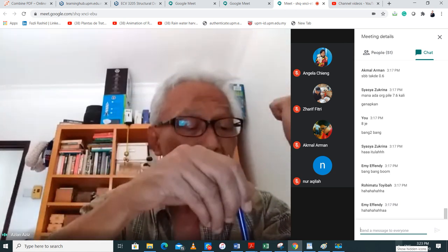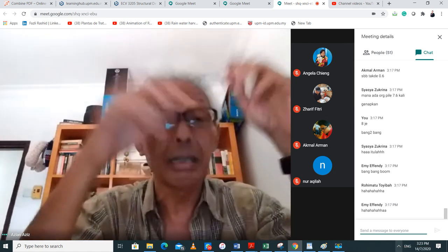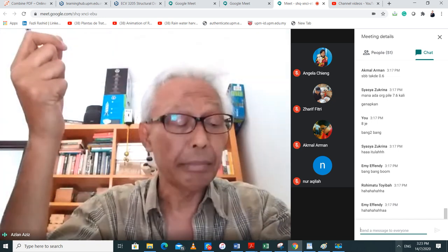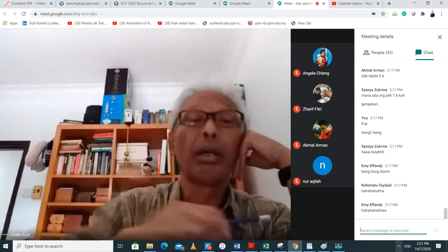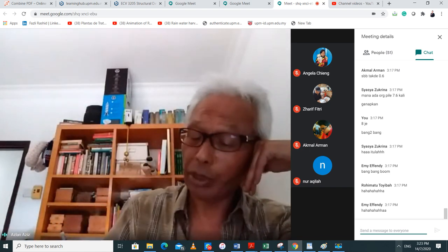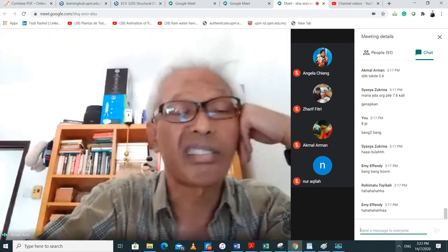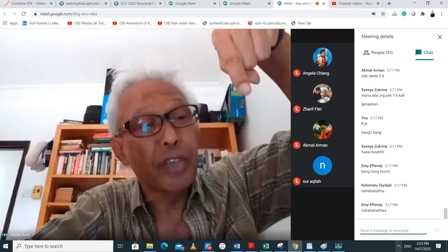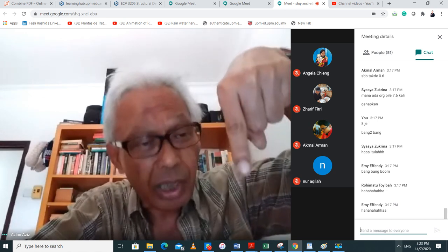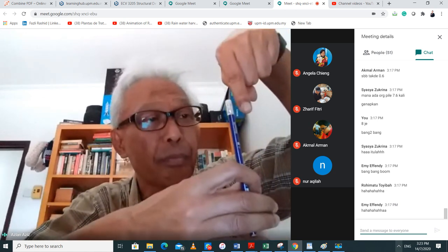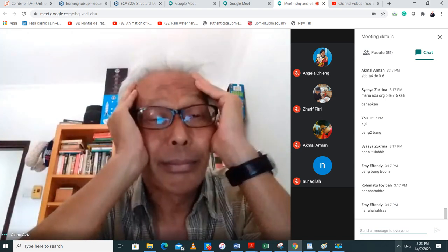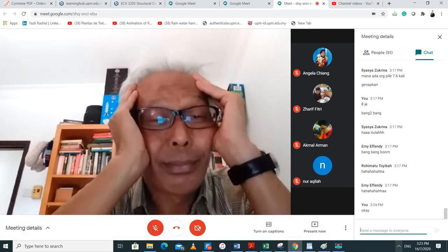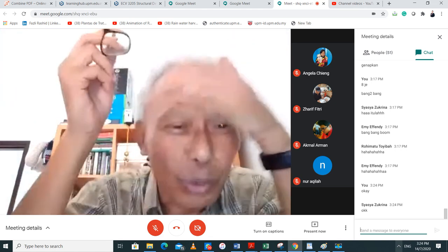So between 9 meter and 10.5 meter, 421 at 9 meter, 605 at 10.5. If I interpolate, I will get this value at 10.2 meter, which is going to be equal to 563 kilonewton of the shaft friction of the pile in this direction. It's going to cancel my uplift load from the water. Okay or not okay, guys? The shell says okay, but this is okay.